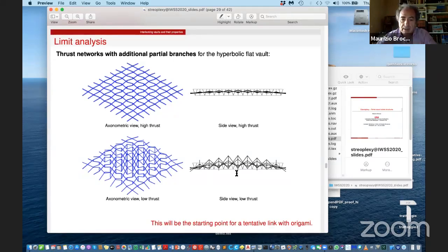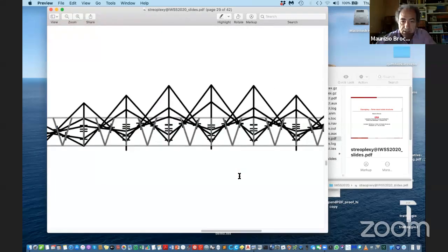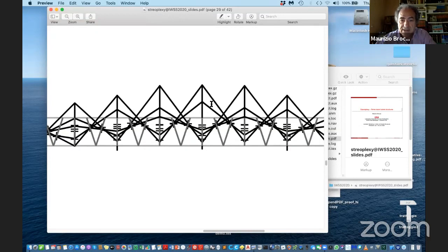And so then this geometric ratio is rather in the local stuff. You see here the line of thrust, it's out of the vault, but the resultant is in the joint. So this is a force passing from one block to the other. It is in the joint, so this is stable, but then it is equilibrated with another force which is in the other joint, stable also, and the two of them have a resultant that is out of the thickness of the vault. So this is why you cannot think of the vault as an inverted catenary, because if you do so, then you have to assume a kind of virtual thickness that is higher than the real one because of the wedge effect.